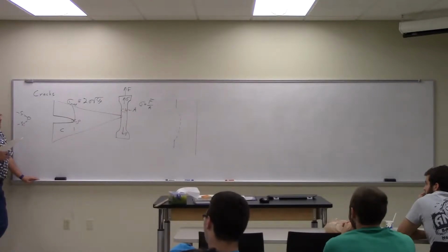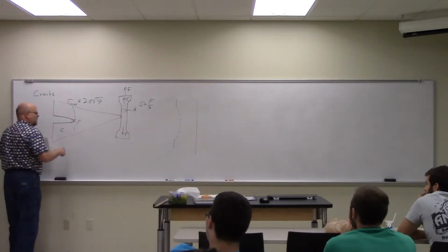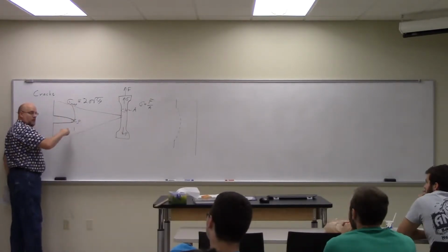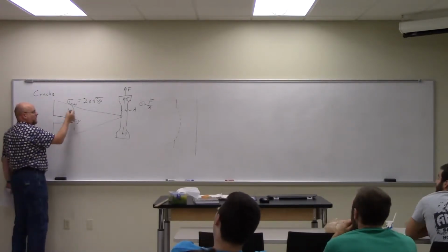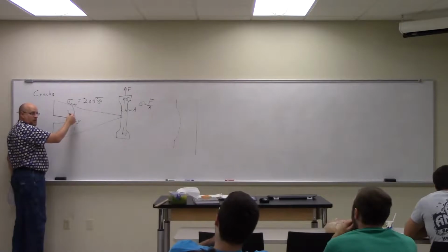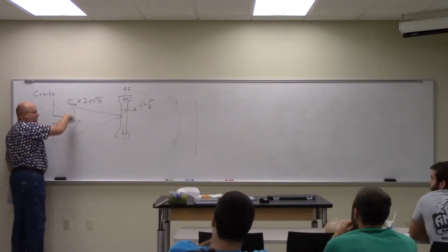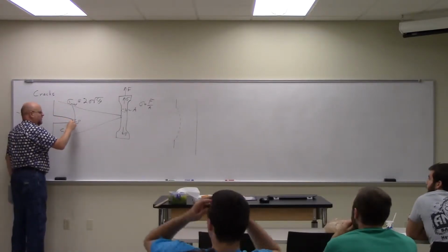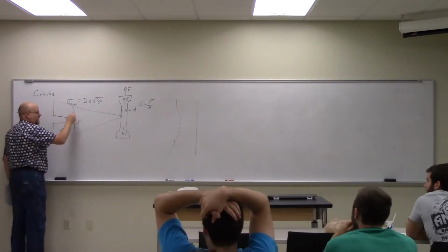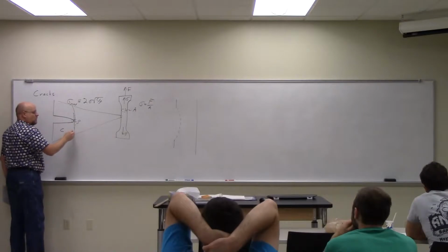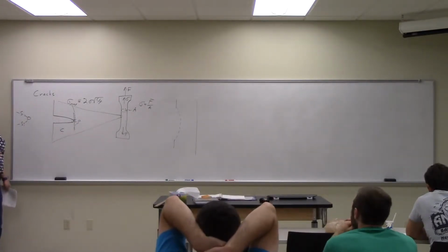Yeah. So there would be a different stress state. If there's a crack going this way, there would be a different stress state at the tip of that crack, because I'm not pulling that crack apart. I'm pulling it in the vertical direction here. So if this crack grew into a crack up and a crack down, then effectively what I've done is dramatically increased the crack tip radius of curvature.